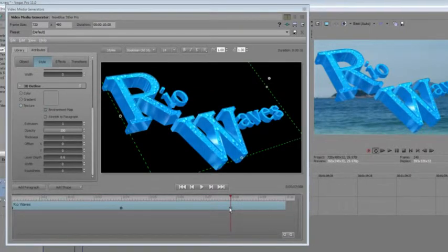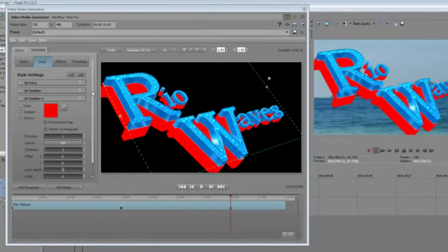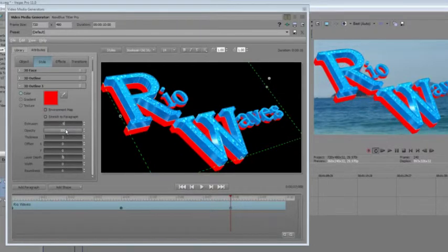Now, as I mentioned earlier, you can add these style settings, both the 2D and the 3D. And as I did here, I added a 3D outline. Well, maybe I want another 3D outline. Just choose it again, and there I have another one. Why might I want to do that? Well, I might want to start building some sort of an effect on this text. So let's say this extrusion is way too deep. Let's make it maybe just 0.5. Actually, let's make it 0.25.